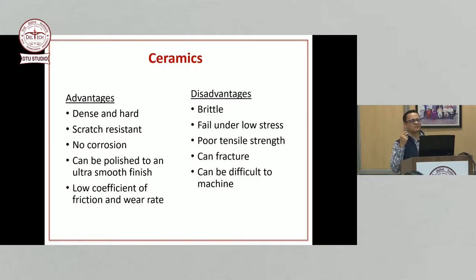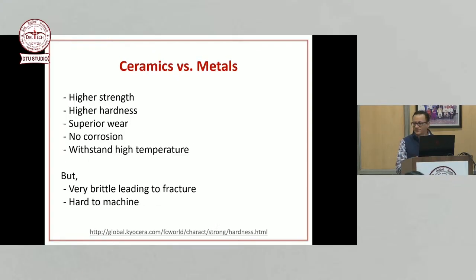And think in terms of a bone implant or a hip implant. If you have a ceramic somewhere, it can crack very easily, right? Yes, ceramics are usually heavy as well. Yeah, so how does it go with the part they're replacing? Because in the body, they are not making the whole implant of ceramic, right? I'll show you that hip implant a little bit after a few slides, how only one part of that implant can be metal and another part can be ceramic or polymer. Yeah, actually in 1 or 2 slides it's coming.